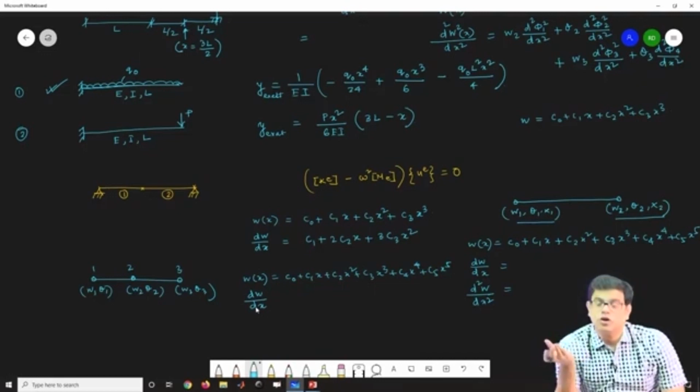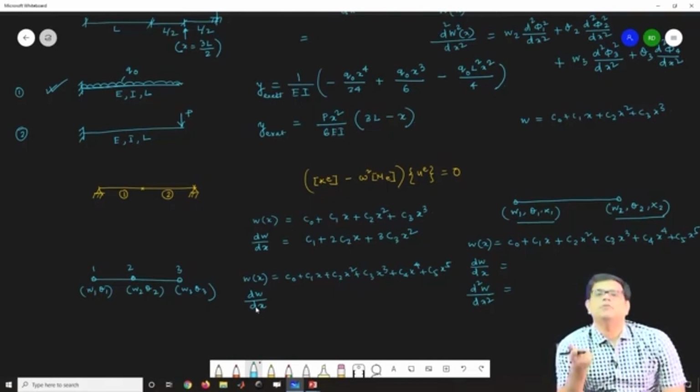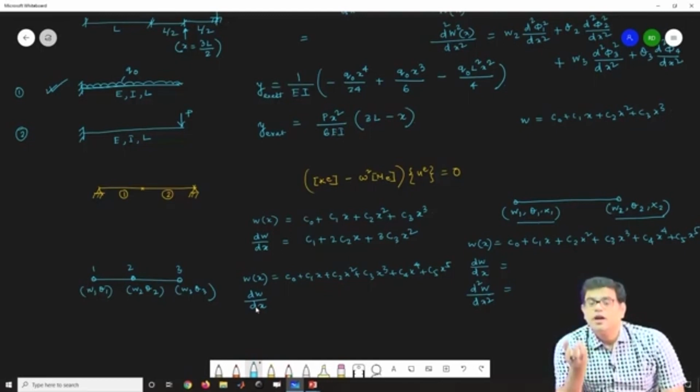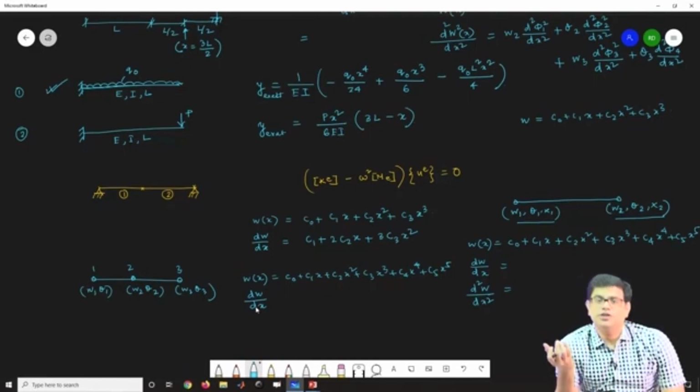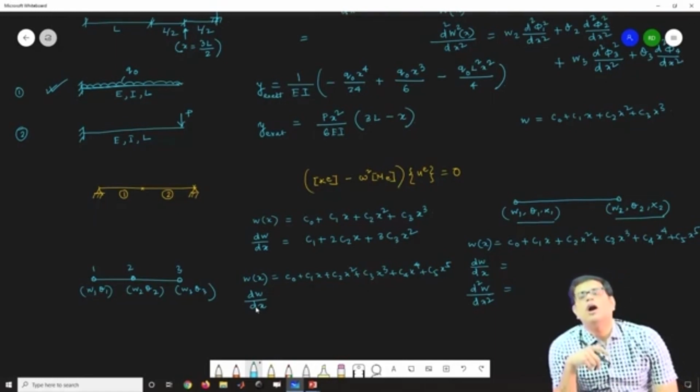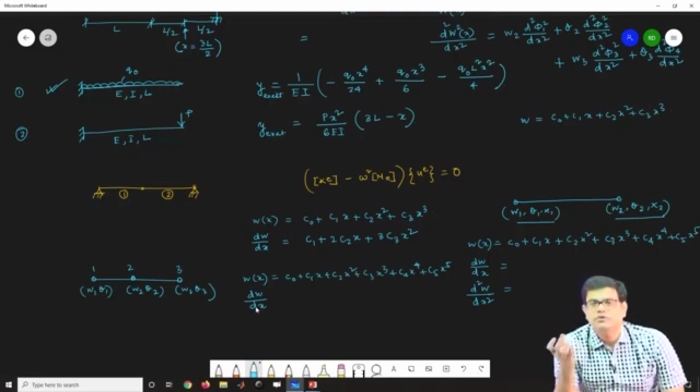So this is the possibility, even though these elements are not standard elements, because we can always refine the element to increase the number of nodes or degrees of freedom in the system. While doing finite element solutions, you have to keep in mind polynomial refinement or mesh refinement, which is popularly known as increasing the number of elements or increasing the degrees of freedom. So there are two possibilities. Generally mesh refinement is very much preferred, because polynomial refinement is not always useful.